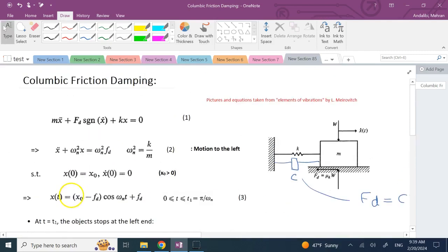Now the question is, if instead of this viscous damper, we have a Coulomb friction. So the force is Fd equals mu k times N, where here N is the same as W, right? In that case, friction is also going to dissipate the mechanical energy of the system, the momentum, or the potential energy to begin with, or you can start with momentum, or both of them, and over time converts it to heat, and the system amplitude starts to go down and shrink. The question is, what kind of response do you get? What kind of shrinking in amplitude do you get? Would you get exponential or something else? This is what we are going to talk about.